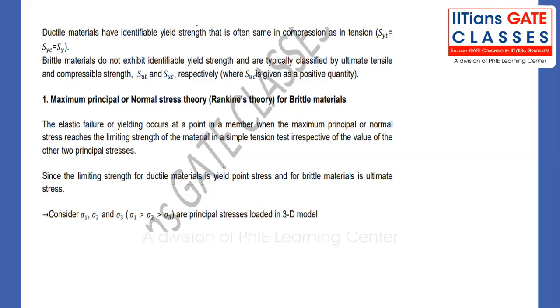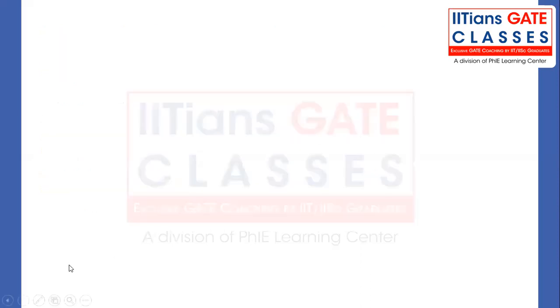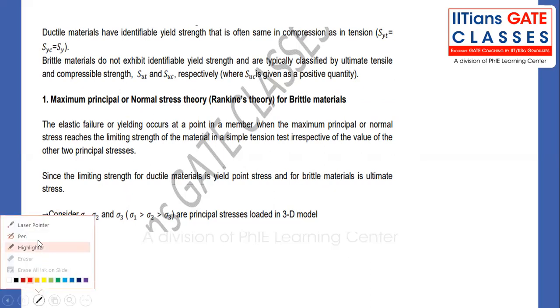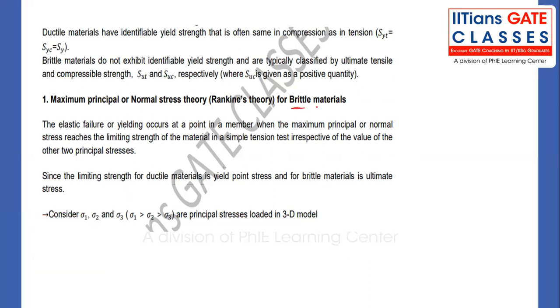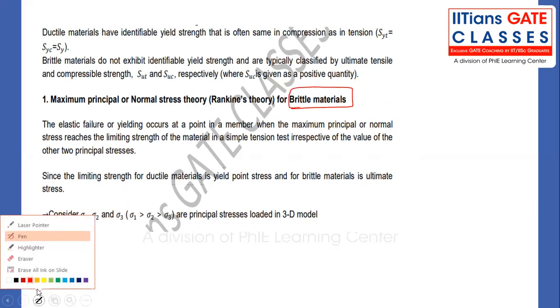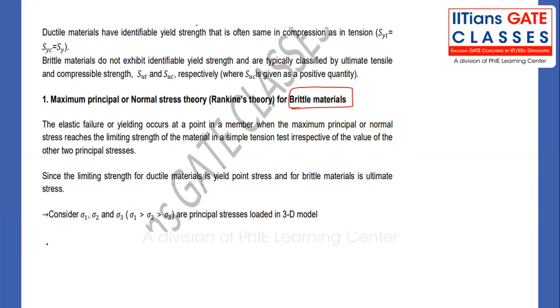So maximum principal stress, or Rankine's theory, is basically suitable for brittle material. Why it is suitable for brittle material, we will see. This is an important point. It is not that much suitable for ductile material.